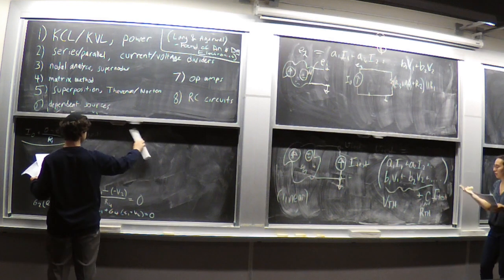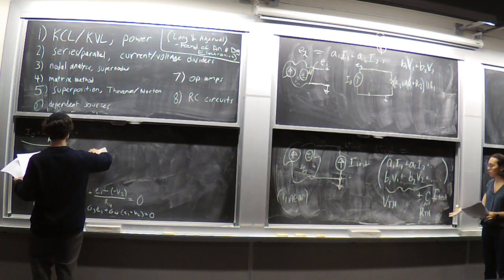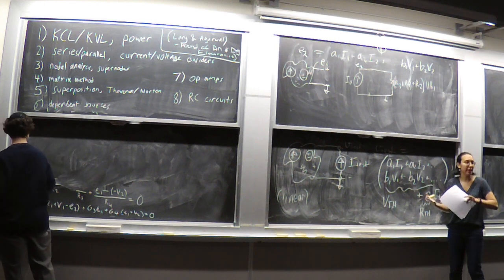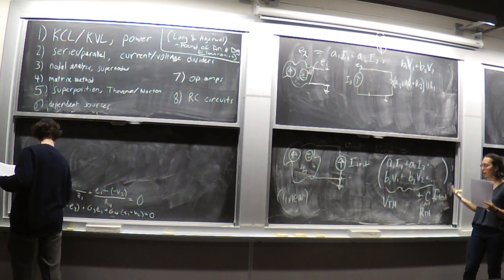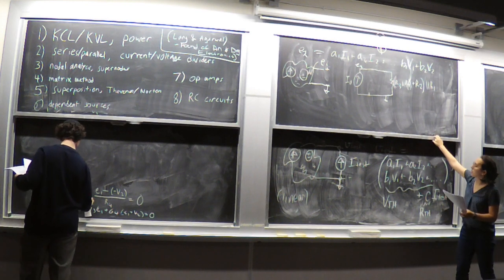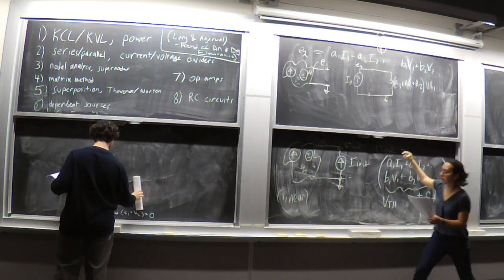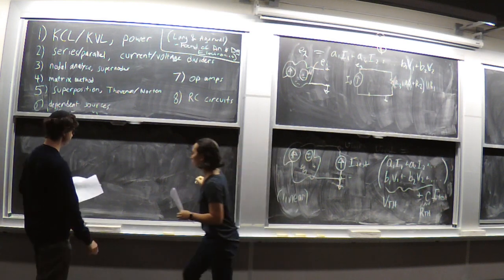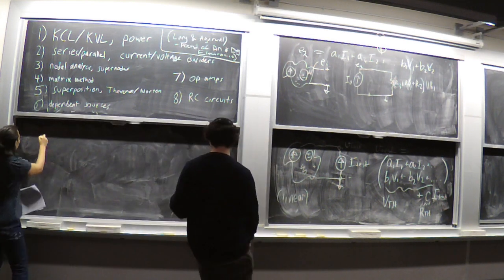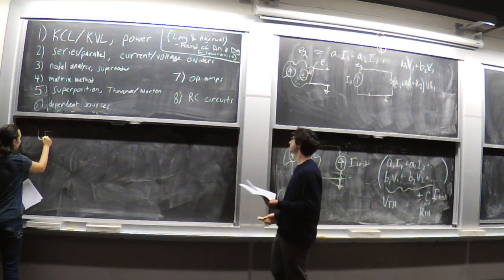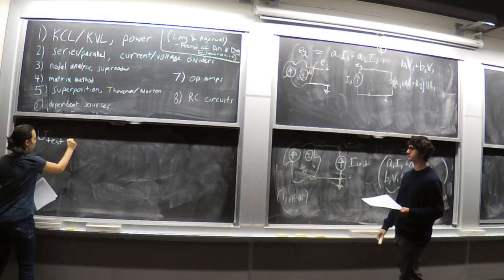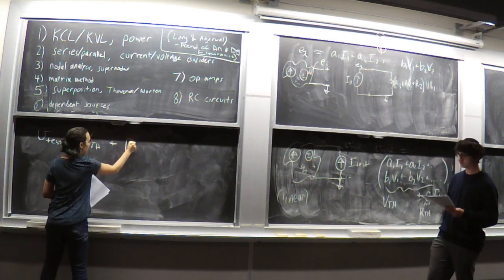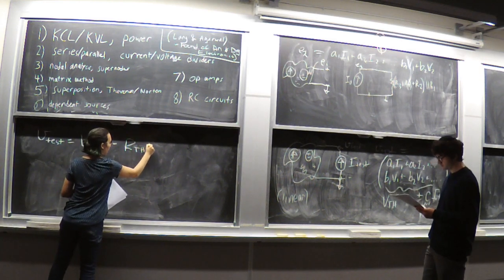So when you see a Thevenin voltage and a Thevenin resistance, what that really is saying is we had some big circuit and we didn't care what was in there, and we're just trying to summarize it. What that equation leads to is the following: V test equals V Thevenin plus R Thevenin times I test.